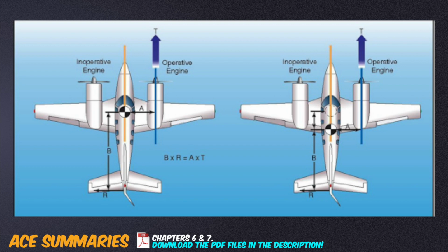VA is the maneuvering speed at which full elevator deflection first causes a stall to occur at the load limit factor. It is specified in the manual. VMCG and VMCA vary with center of gravity positioning, as the yawing moment of the tailplane and arm of the asymmetrical thrust producing engine is dependent on this factor. Aft center of gravity requires a higher VMCG/A because of the reduced tailplane moment. VMCG must be less or equal to V1. VMCA must be less or equal to V2.